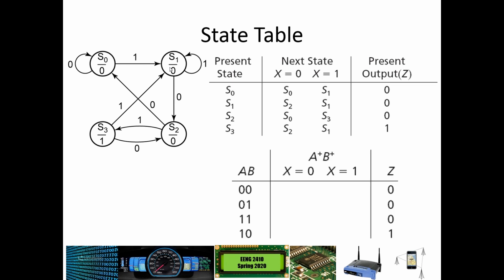And from here, it's a matter of choosing binary for each of the states. Now, we have 4 states, and so what that means is we need 4 binary representations, and so we can just use 2 bits to do that. And so in the previous example that we had gone through with developing a Mealy circuit, we only needed 3 states, so we still also used 2-bit binary, but as it turned out in that example, we did not use all 4 of the combinations.